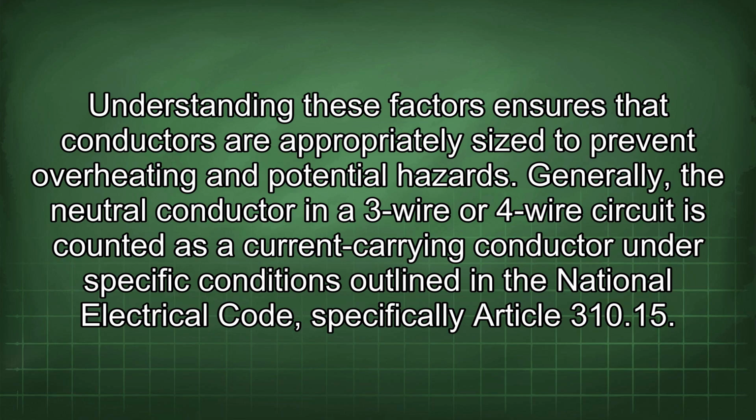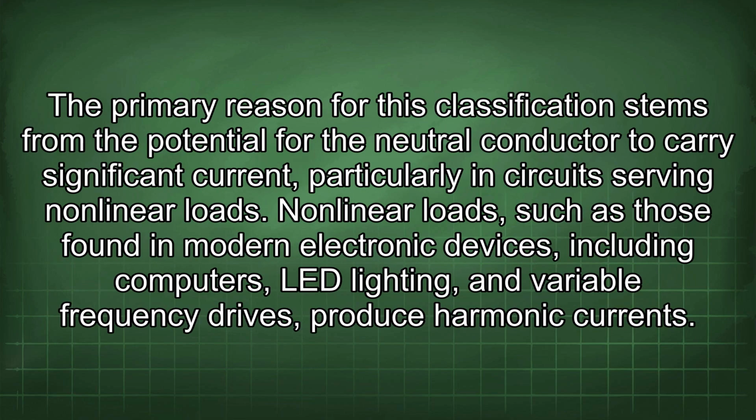Generally, the neutral conductor in a 3-wire or 4-wire circuit is counted as a current-carrying conductor under specific conditions outlined in the National Electrical Code, specifically Article 310.15. The primary reason for this classification stems from the potential for the neutral conductor to carry significant current, particularly in circuits serving nonlinear loads. Nonlinear loads, such as those found in modern electronic devices, including computers, LED lighting, and variable frequency drives, produce harmonic currents.